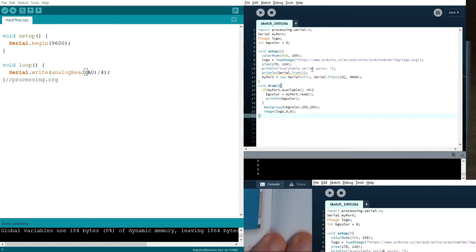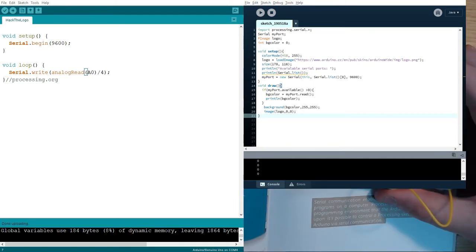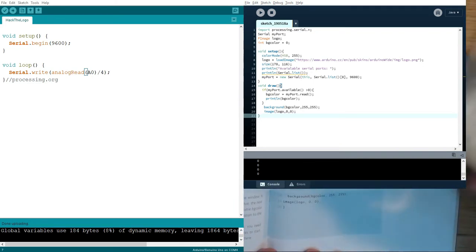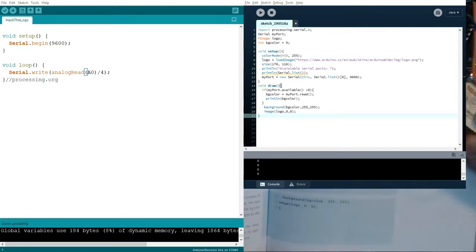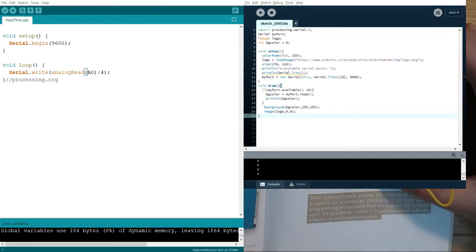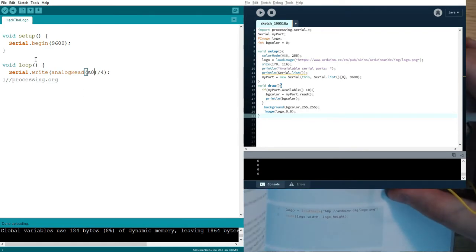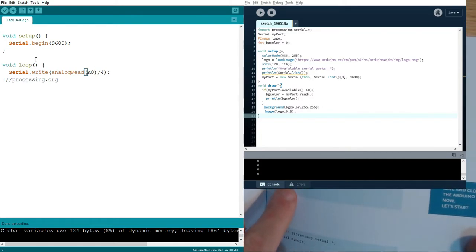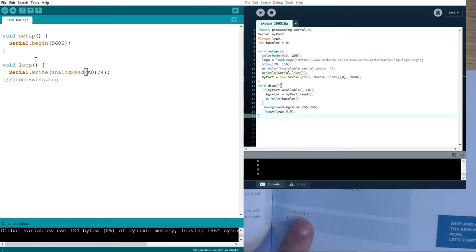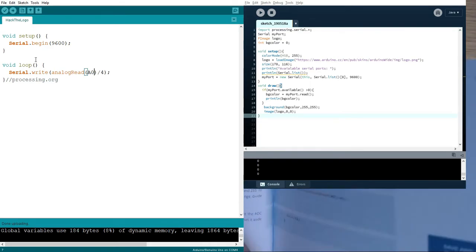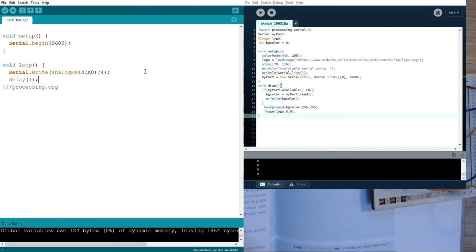Now I'm just going over the pages again. Maybe it must be reading from the same port or something. I mean, I don't see it not. Serial begin 9600. That's the Arduino code. Serial.write. Oh! Okay, I've left out a small delay. I need a delay 1. Now, I have no clue how much this actually affects things, but it's probably not helping things.